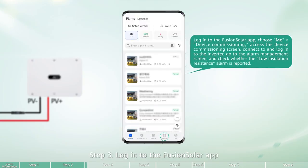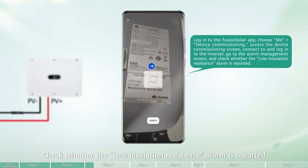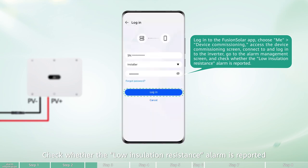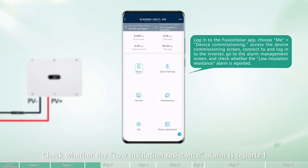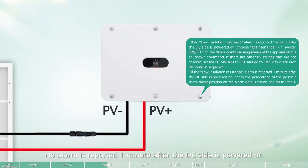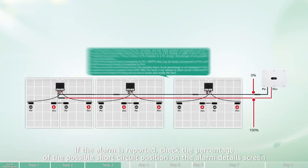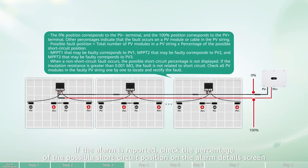Step 3. Log in to the Fusion Solar app. Check whether the low insulation resistance alarm is reported. No alarm is reported 1 minute after the DC side is powered on. Log into the app and send a shutdown command. If the alarm is reported, check the percentage of the possible short circuit position on the alarm details screen.